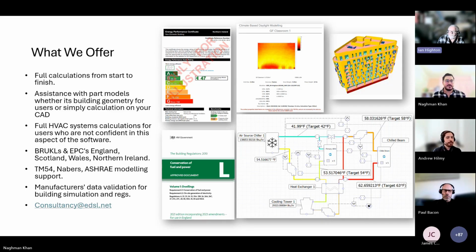Yeah, the other thing I meant to mention is when I was showing that simulation, you probably noticed sometimes it goes quite fast and sometimes a bit slow. And what's fascinating to me is if you've got good control strategies in your model, it tends to run quicker. It's more stable. There's less numerical iterations required because it's a sort of stable system.